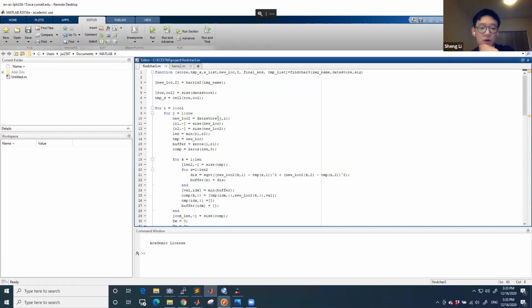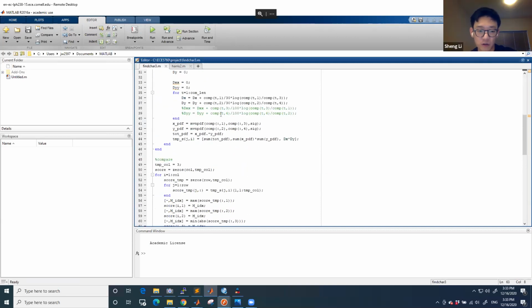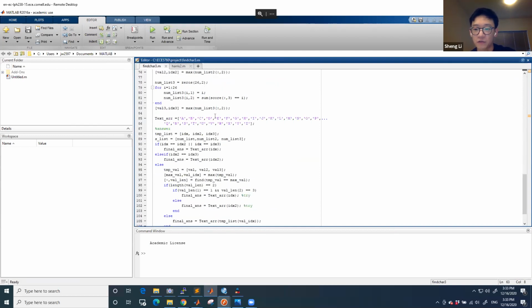So for the convolution part, the way we did the Gaussian, we can just save the kernels: the Gaussian filter and its derivative along x and y, two or three kernels. We just store them in the FPGA. So when an image comes into the FPGA, we can use the derivative of Gaussian along x to convolve with the original image.